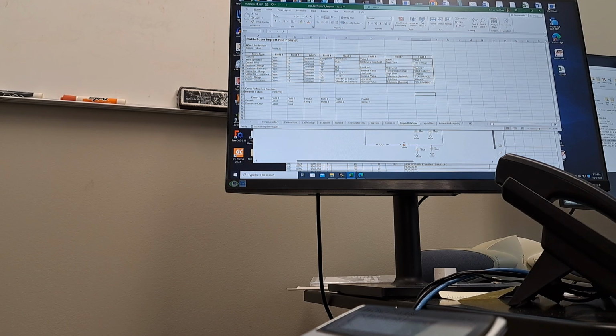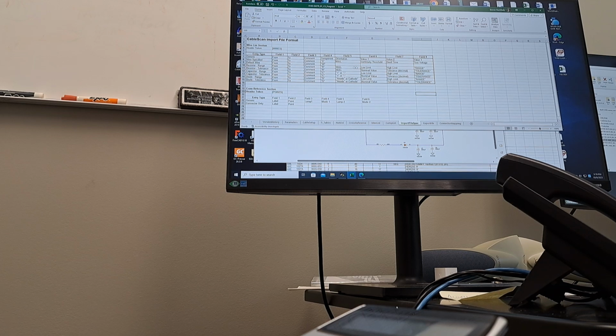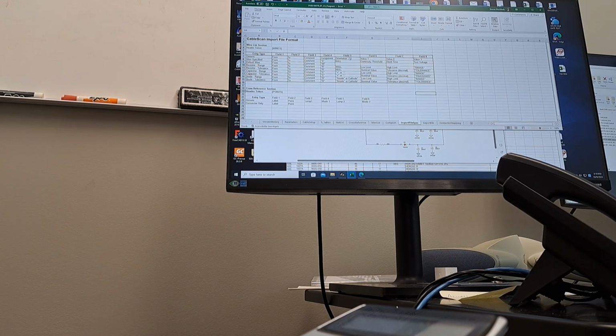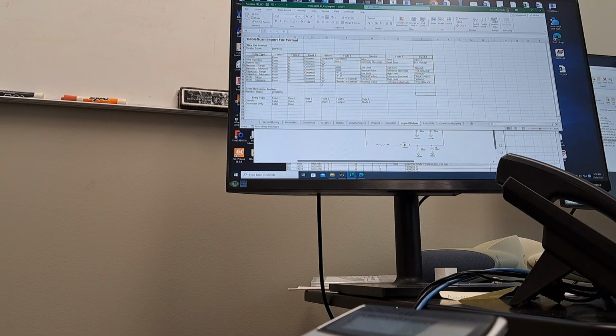Resistors, and remember I told you it's range and tolerance. So for resistors, you can put range and tolerance. Capacitors, and then these are the things that you want for that. For the orientation field, it can be a plus or a minus, and then for a diode you say anode or cathode, and then it'll be there. It's all done.